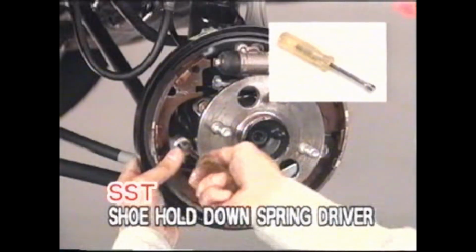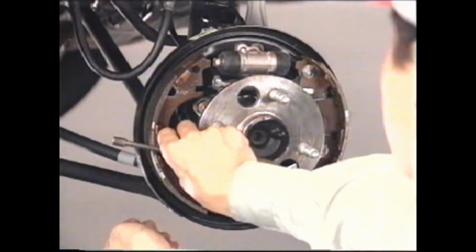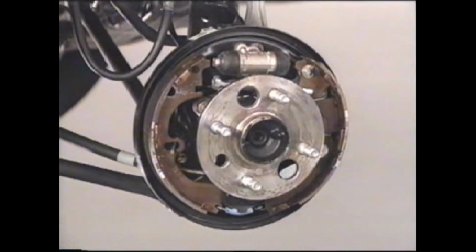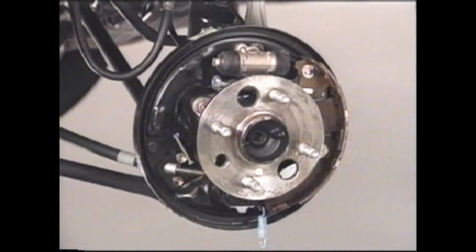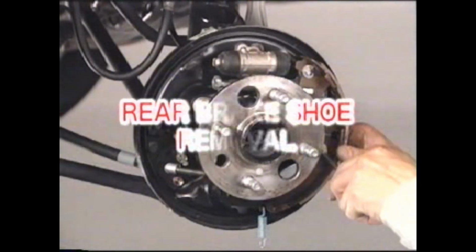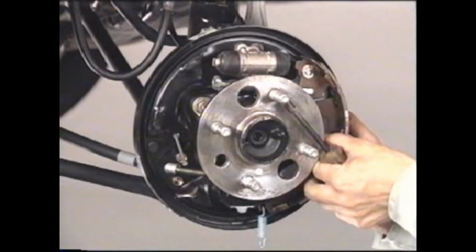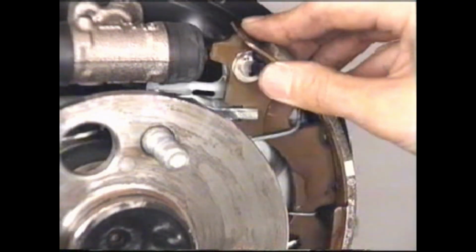Hold the end of the pin and turn the hold-down spring 90 degrees using the SST. Remove the anchor spring and then remove the front shoe. As for the rear shoe, hold the end of the pin and turn the hold-down spring 90 degrees using the SST.